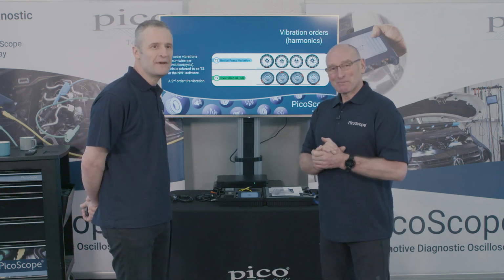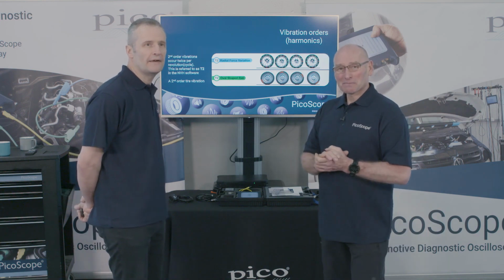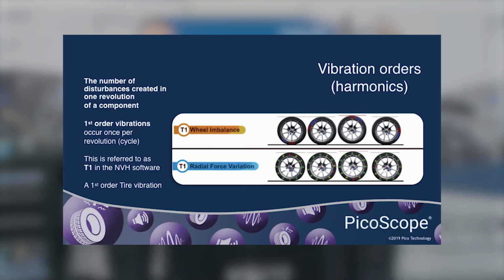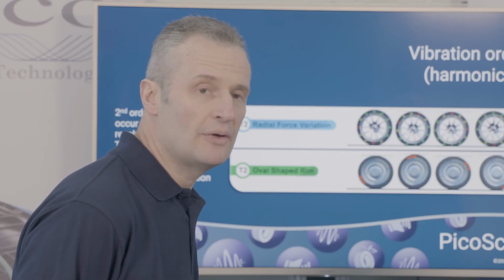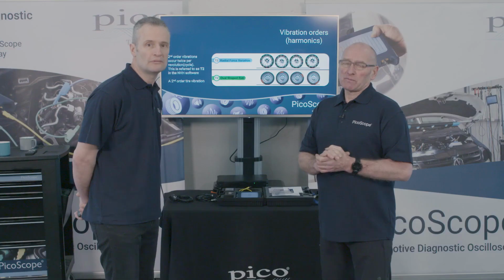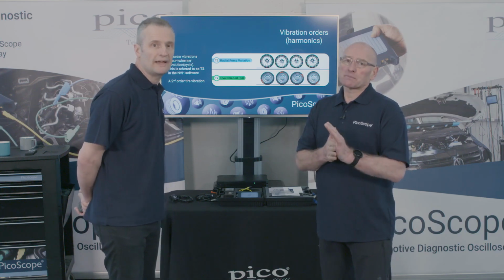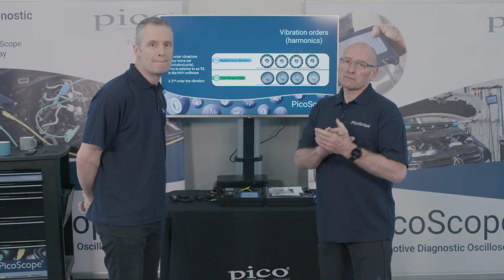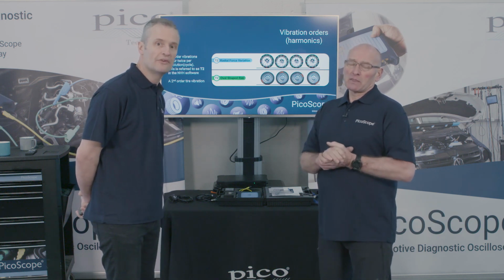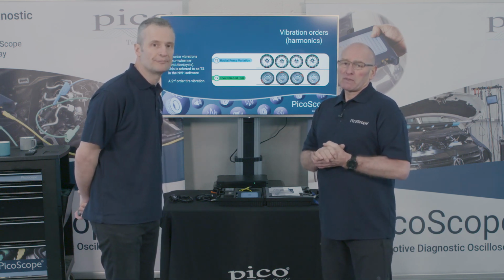There's certainly, when we're road testing, you'll identify that when you accelerate a vehicle you may see a T2, a second order tyre vibration. If you think about that, that tyre has changed shape under acceleration. The same as it could well do cornering, but most certainly when you brake as well, that tyre will change shape. So when you're road testing for vibration, again, it's this all-important thing about road testing with the customer under the customer's driving conditions.